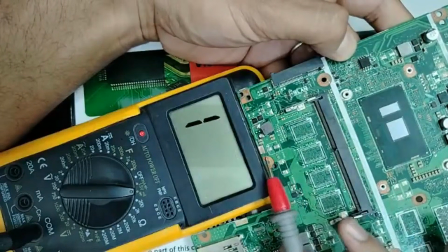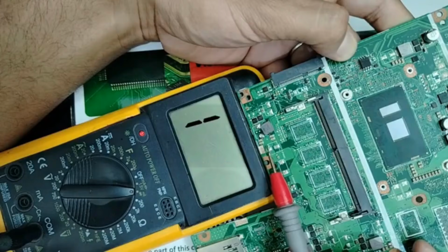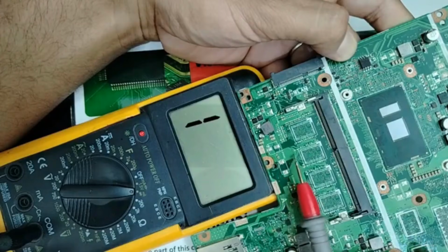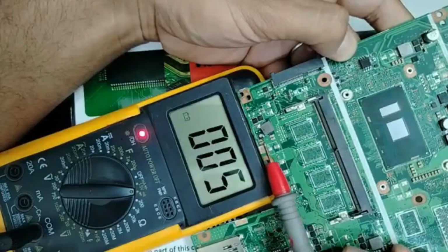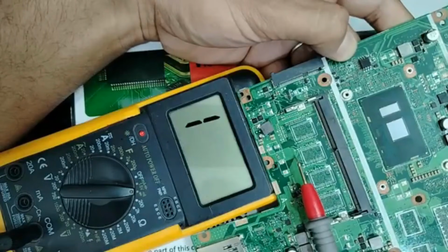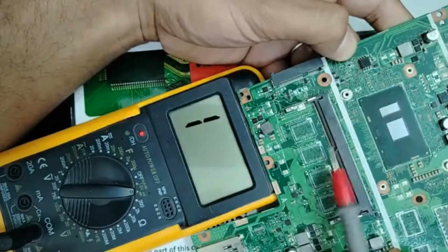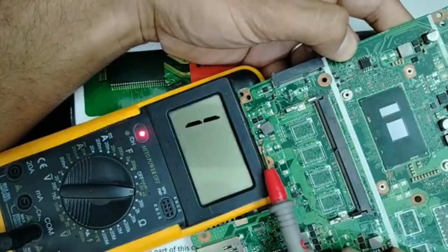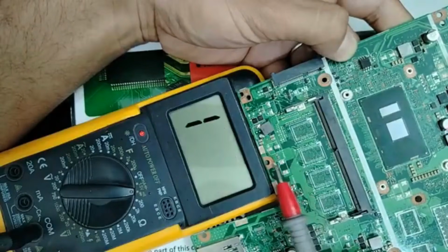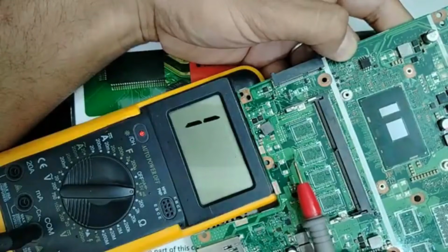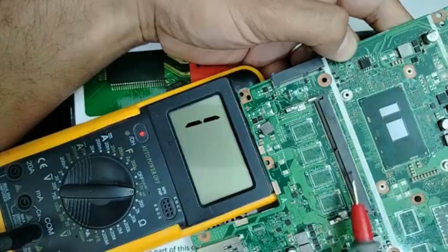From the manufacturer is not connected. If we follow this path here, we have these dots. Do you see these dots, my friends? These dots mean this part here is connected to 1, 2, 3, 4, 5 parts in the motherboard. It means these capacitors could be shorted, or the short could go here. So we should look in the motherboard.